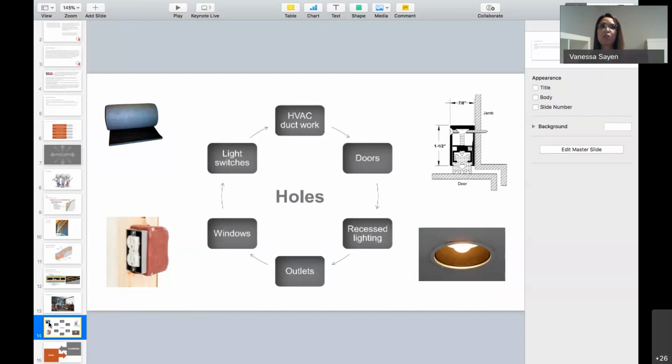So same thing for sound. It's not an exception. So small gaps between drywall, holes in the drywall, electrical outlets, air conditioning vents, around the door, all of this and more will allow sound to escape from one room and penetrate the other. There are other areas also that need to be addressed, like the light fixtures, the ducts, the pipes. Those are going to make sure that the sound travels as well.